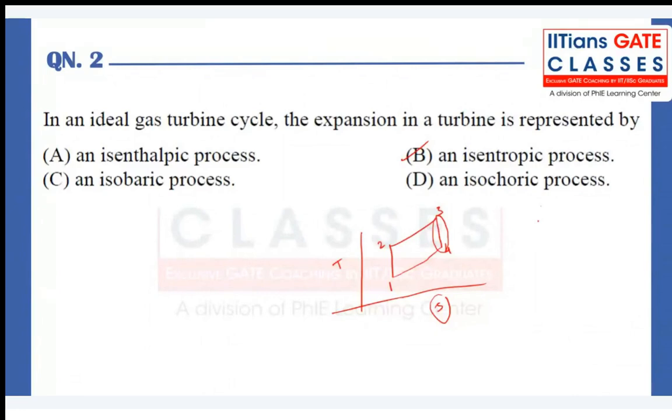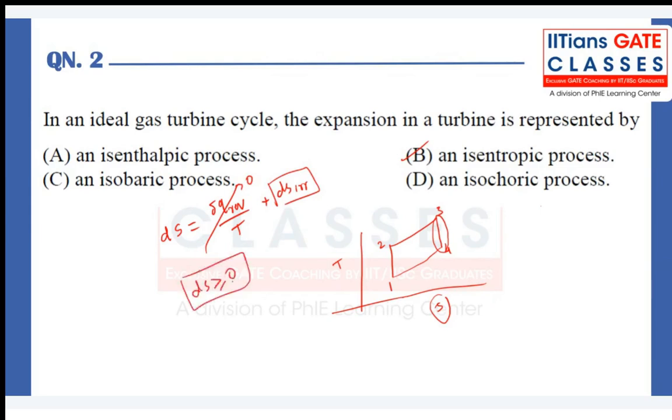So, by the second law, if I have to put it in an exact way, the change in entropy is due to a reversible part, delta Q reversible divided by some reference temperature, plus ds irreversibilities. This part can go to zero in an adiabatic process, but still this irreversible part can exist. So that makes ds greater than or equal to 0. For a pure adiabatic process, ds is greater than 0. For an isentropic process, ds is equal to 0. So this is what happens.